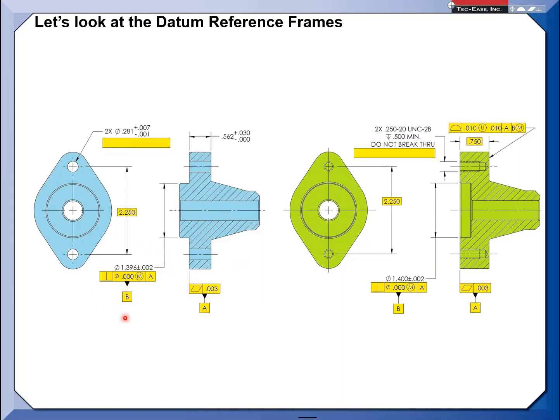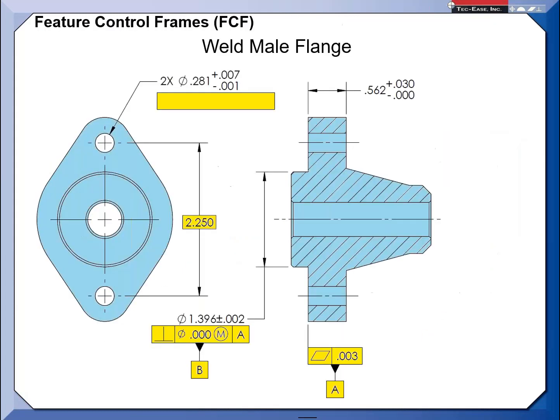And then the relationship of the pilot diameter fitting within the hole relative to this. So let's take a look at this. Let's first talk about this one here, because the reason I'm pointing this out is I did get some feedback, asking: if I take a look here, is there a problem that datum feature B, because of the extreme boundaries it may come into, could actually override datum A primary?